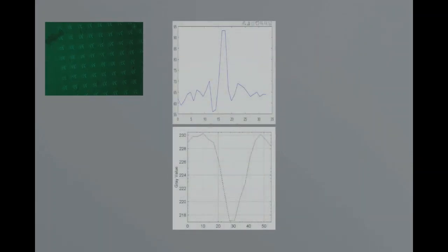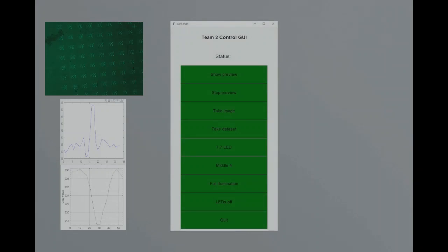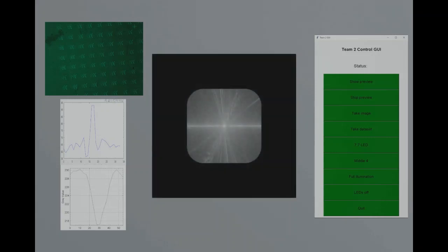The following noteworthy achievements of the project include: successful capture of images resolving 6-micron features on a sample in reflectance mode using on-axis illumination. Contrast analysis showed an improvement of 21.7% over the Sentinel system's imaging capabilities. Production of a GUI for the embedded system with consideration to future use cases. Creation of a Fourier ptychography algorithm and simulation of a dataset to test effects of varying parameters.